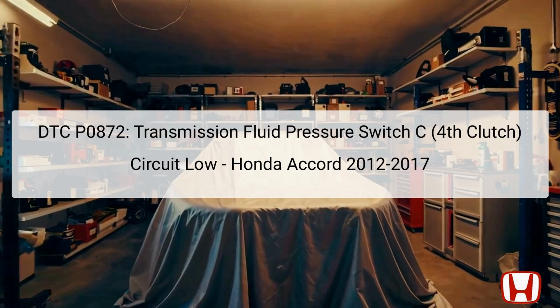The Diagnostic Trouble Code, DTC P0872, indicates an issue specifically related to the transmission fluid pressure switch C, which serves a critical role in regulating the transmission fluid pressure corresponding to the fourth clutch operation. In the Honda Accord models from 2012 to 2017, this switch is integral to the transmission's ability to shift appropriately